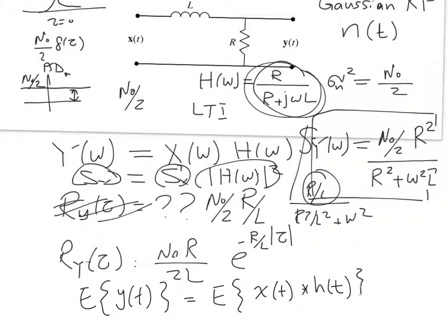The convolution is an integral and time shifting, right? Assume that you do the time shifting with h of t, so that things are easier. Then you will end up with h of t outside the expectation, and then the expected value of x of t, correct?